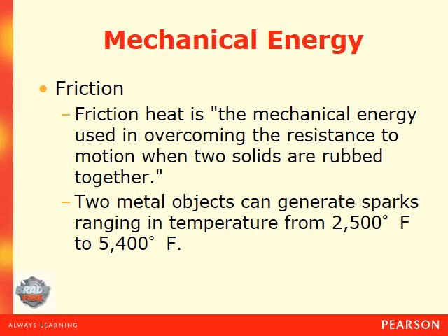So how does that energy transfer form? And that is done through the process of friction in terms of the brake pads. The drums, which are behind the wheels, have another piece of metal or metal type stuff that presses against it, causing friction. So that friction is producing heat, and that heat is coming from the energy of the movement of the car.